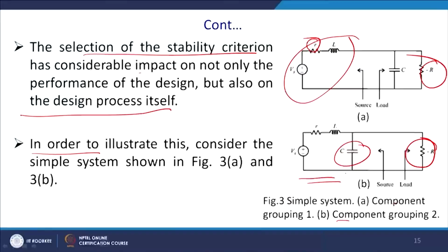But since a more stringent condition arises once you have negative resistance, for this reason this example has been chosen, where you have a CPL, and students are requested to validate this whole phase margin gain margin method by other kinds of constant loading, and see whether this control bandwidth increases or not.